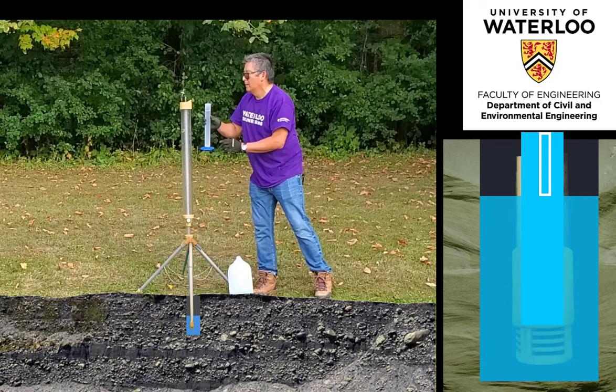The height of the water rises in the borehole to the elevation at the base of the air tube, equilibrating the atmospheric pressure conditions between the reservoir and the borehole. The height from the bottom of the finished borehole to the base of the air tube is the resulting hydraulic head delta H used throughout the test.